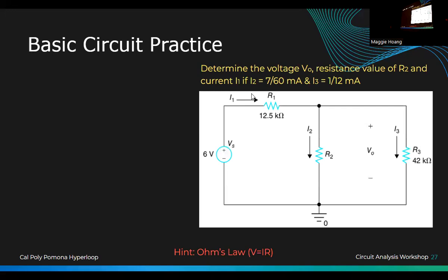You make those in parallel on the right, and then you make them in series, and then you find the total current. Or you could just make those parallel and do a voltage divider. We haven't learned voltage divider yet. Oh, in series. All right, what was the first step? R2 and R3, you have to do an REQ equation. But we don't seem to have a number for the second resistance.